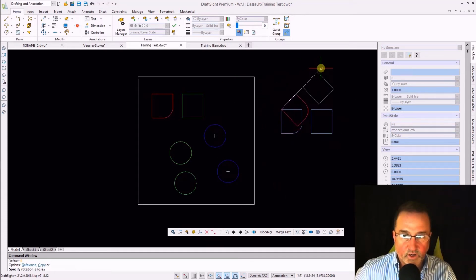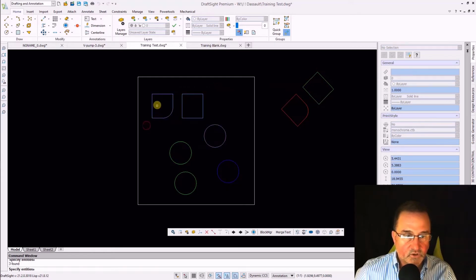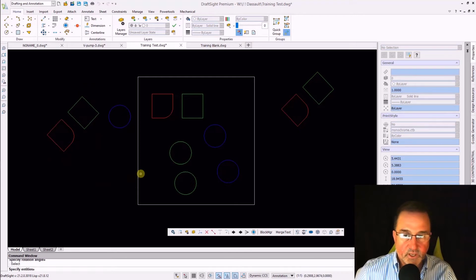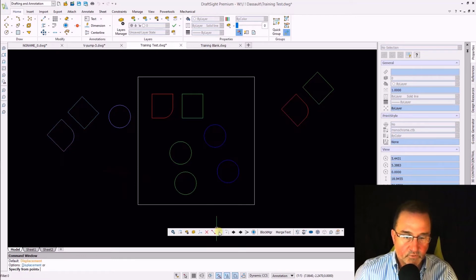And notice I go right into the rotate command. And I can do this again. So pick a point, go over here, I pick more objects. But basically, it's repeating that loop of copy rotate all in one thing. So sometimes, for instance, if you're placing certain types of blocks, furniture, different things, you want to move things around, really useful command for just doing that sequence by 1 or 2 picks. So it makes it really, really nice.